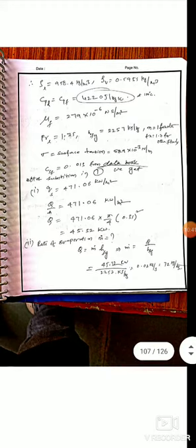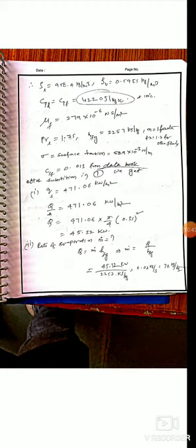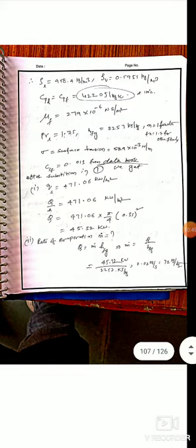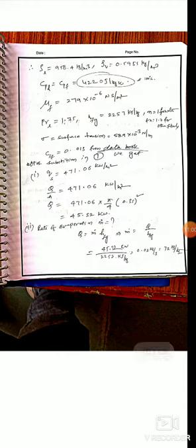Now we substitute the area and we get the heat. Q is equal to 471.06 into pi by 4 d square. We know the diameter of the pad is 350 mm. Convert it into meters and square it. You will get pi by 4 d square, and Q is equal to 45.32 kilowatts. So this is the rate of heat, the power supply must be 45.32 kilowatts.